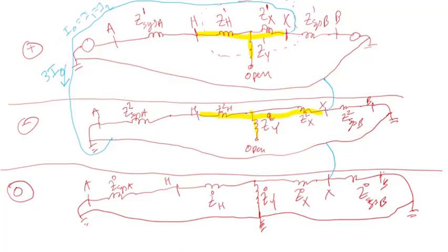But obviously what would flow through phase A? So in this case, we'll assume a phase A line to ground fault. So basically this here, phase A, it's 3I0. That's what will flow through the system. So now if you notice here, since this is open, it really does not come into the equation.